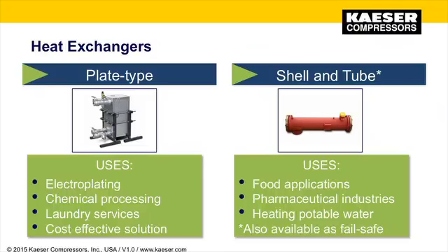The plate type heat exchangers offer a cost-effective way to capture heat from the rotary screw compressor and utilize it to heat water for diverse processes such as electroplating, chemical processing, or laundry services. The fail-safe heat exchangers provide additional protection against contamination of process water or fluids by the compressor cooling fluid.